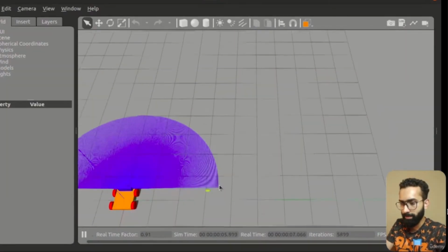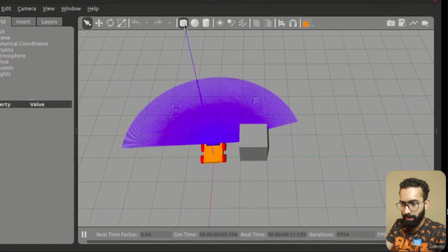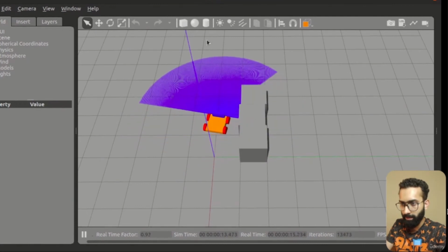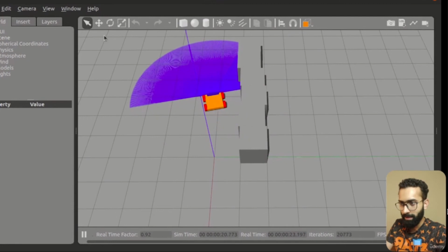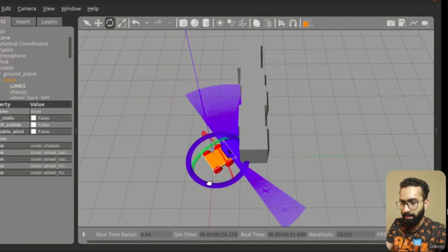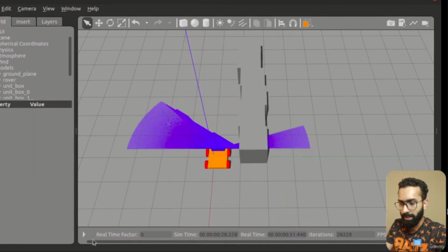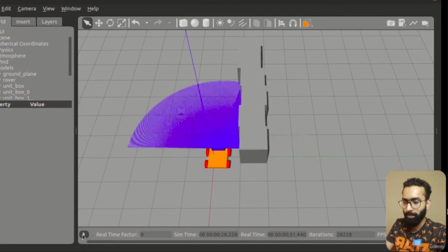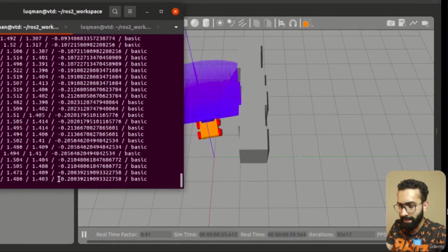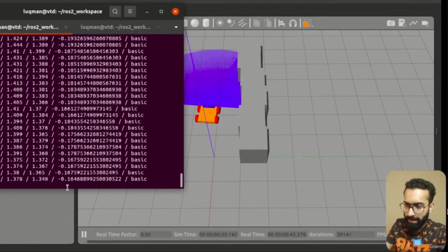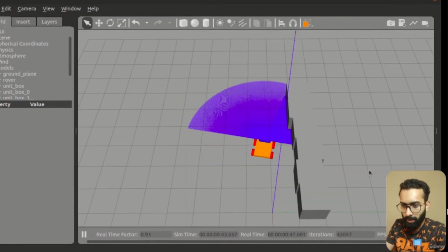If we have a wall, this wall and this wall, again the wall, I'm creating the wall and the robot is moving quite fast. It is following the wall. Let's take a look. If I pause the simulation, let's bring the robot to a point where the simulation is going to say that now start following the wall. Okay, this is the error. The robot is acting on the error. You can see now it is negative and the error is minus 0.14. It is reducing and you can see the robot is coming back to the wall.